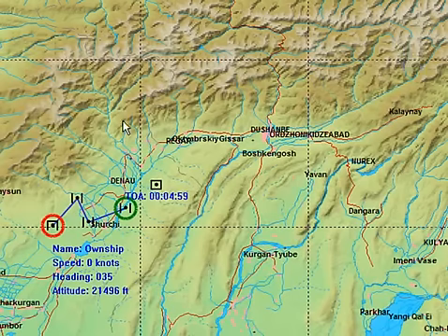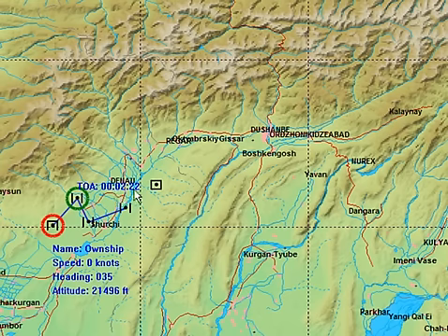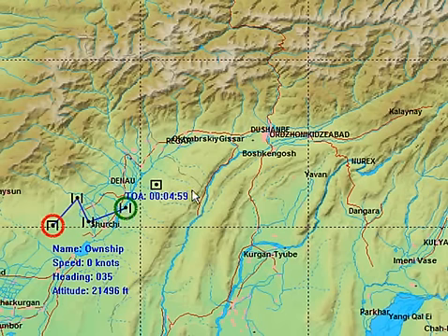Alright, so that's good. Now when I play, and actually I can see what time, it'll be at 2 minutes and 22 seconds when it gets to that waypoint, 3 minutes and 35 seconds when it gets to that one, and 4 minutes and 59 seconds when it gets to that one, assuming it can actually make these turns. If I were to slow down the parameters, the turn rate, for example, were too slow, it would not actually be able to make some of these waypoints. But that's alright, it'd do its best to try and get there. And if it couldn't get there when the time elapsed, it'll just go on to the next one.